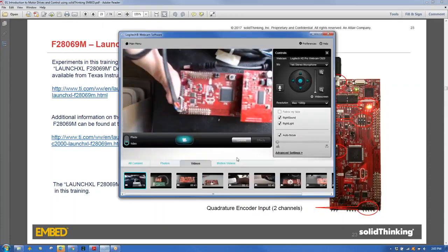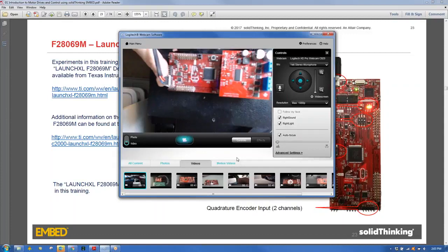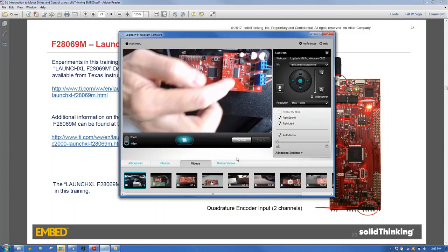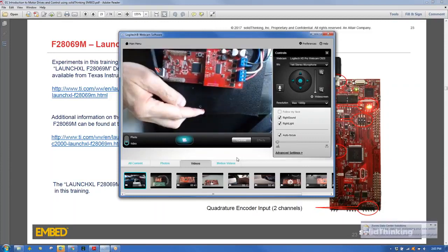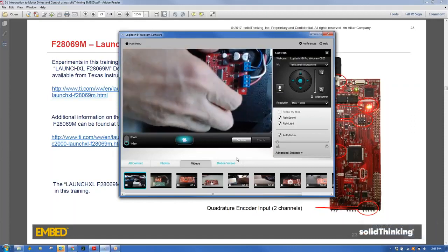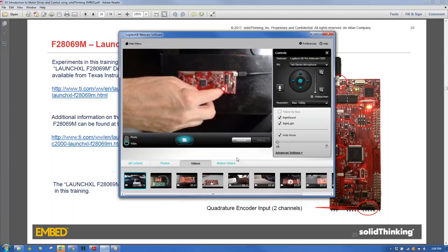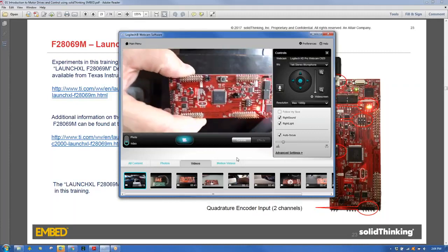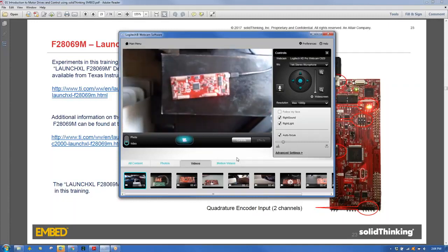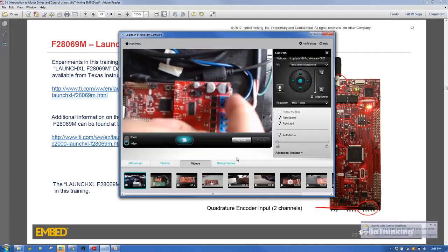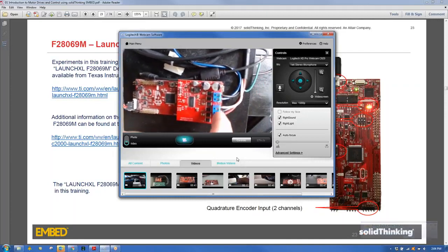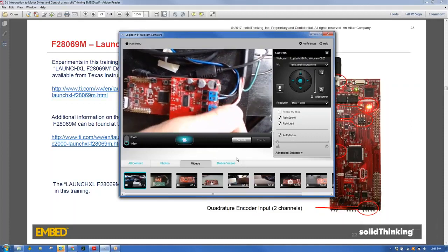So for motor control, what we use is the 6.9M board and this inverter board, which is called a DRV8301 board. This is about a $60 board. It just plugs onto these rows of pins. It just straddles these pins right here. You plug it on and you wire up a 12-volt power supply right here. And this is the 3-phase output up to 10 amps. This will provide to a motor.